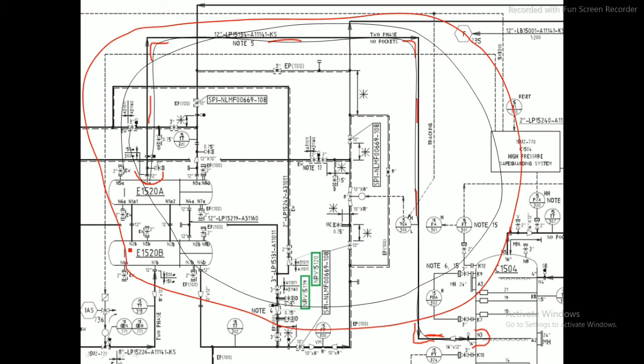So try to understand why he placed the drain over here, and why he placed the spectacle blind over here. You have to understand what components have been placed in the line. Okay, so what these symbols mean, you have to check in the notes. This symbol means that from this point we have to keep this wall at a minimum dimension. You can check the notes for what the star symbol means. It will give the dimension, like minimum it should be 500 or 800 something.